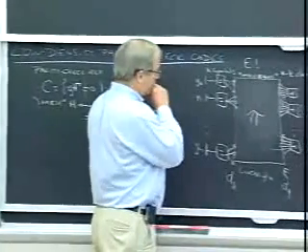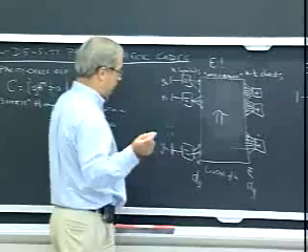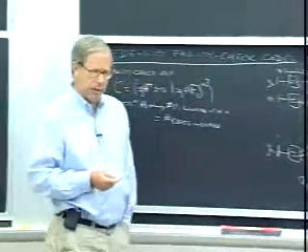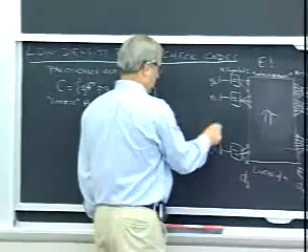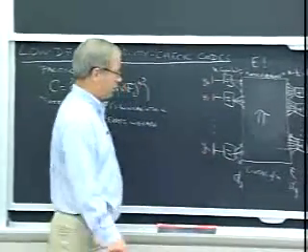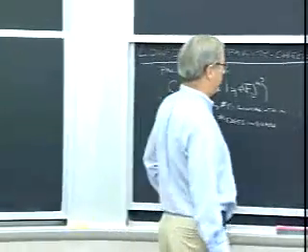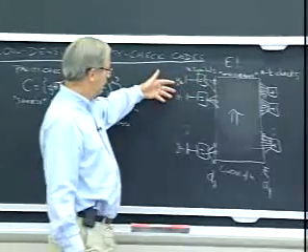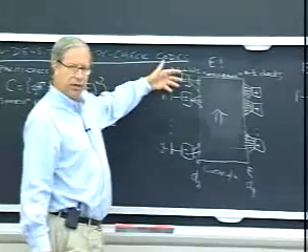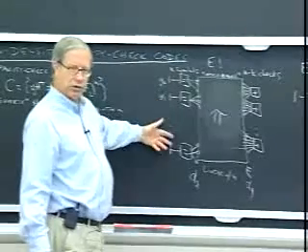But right now we're talking about the decoding algorithm. So the decoding algorithm is pretty much what you would think, I would hope, now that you've seen sum product decoding. You receive something on each of these lines, depending what the channel is. If it's an additive white Gaussian noise channel, you get a real number received vector that gives you some intrinsic information about the relative likelihoods of 0 and 1 on each of these lines.